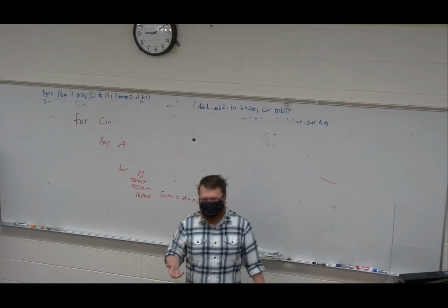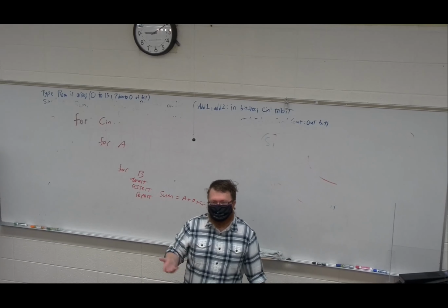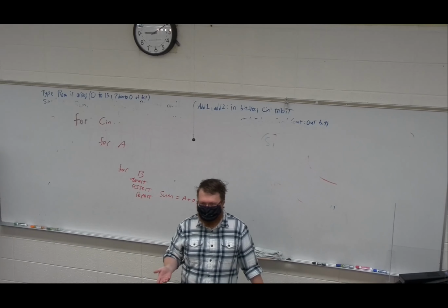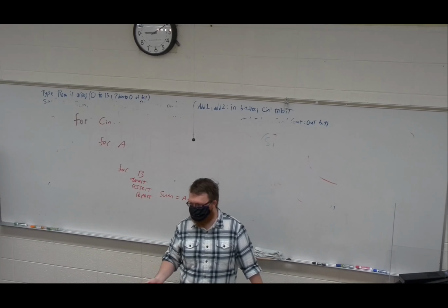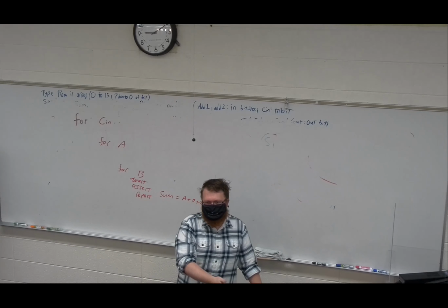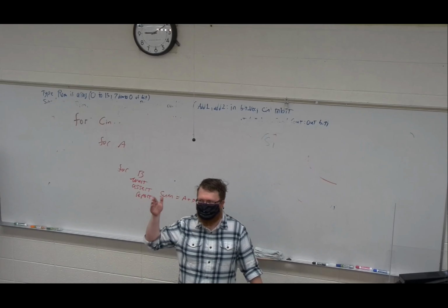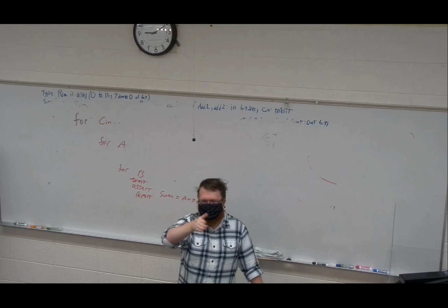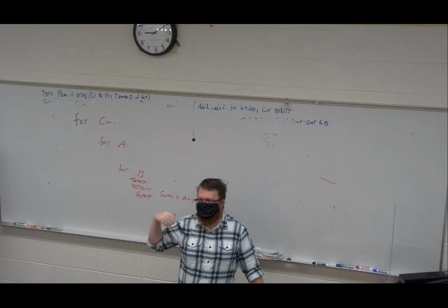So one way of debugging that I've had in the code previously and use frequently is what I call the status lights. These are lights that light up depending on what state you're in, or sequential lights that build up as it steps through some process. You can use these output lights to see where your board is and just look at it.